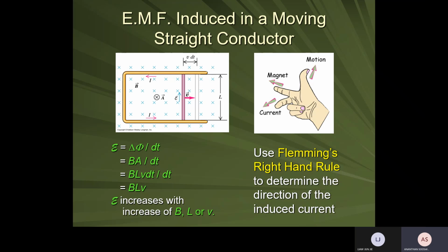Okay, so here, because the v is to the right, so your force is to the right, and the magnetic field is into the page. F, B, I, F is to the right, B is into the page, so the current should be upwards. Current should be upwards in the conductor. Okay. So this is different because it is just a conductor, one conductor.